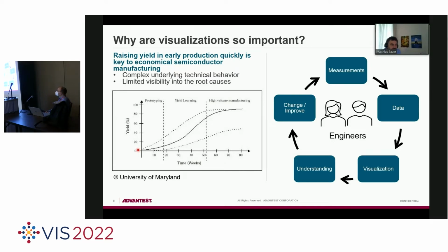As engineers, you need to work hard and look at the measurements, at the data, to improve here, tune the production processes, and understand any imperfections in the design or the process, and where to tweak that. So the essence is that after starting production, there's a yield learning phase, a yield ramp phase, and keeping this phase as short as possible is one of the key success factors for a company.